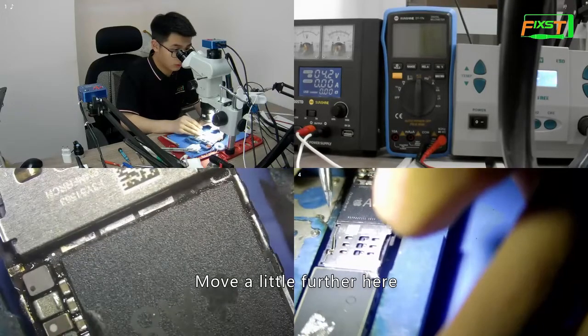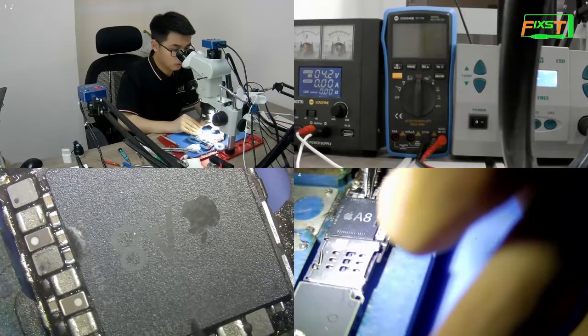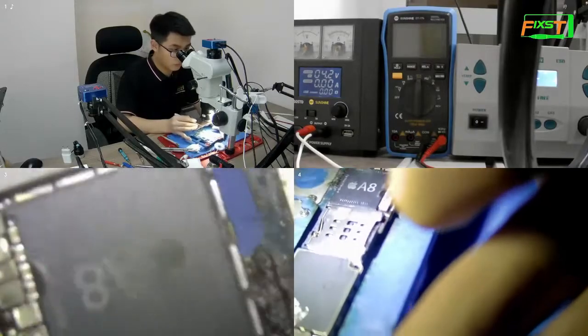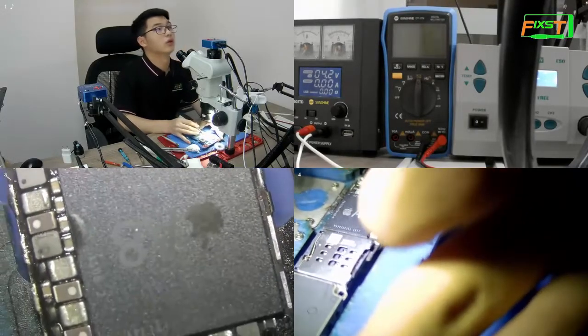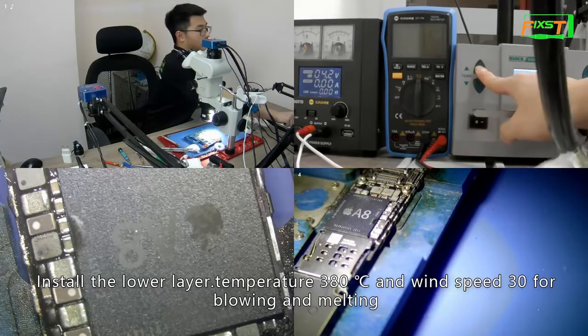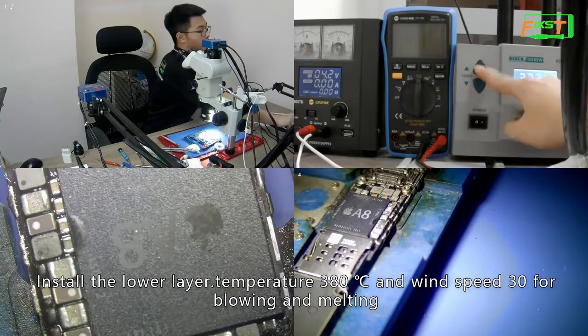Move a little further here. Install the lower layer. Temperature 380 and wind speed 30 for blowing and melting.